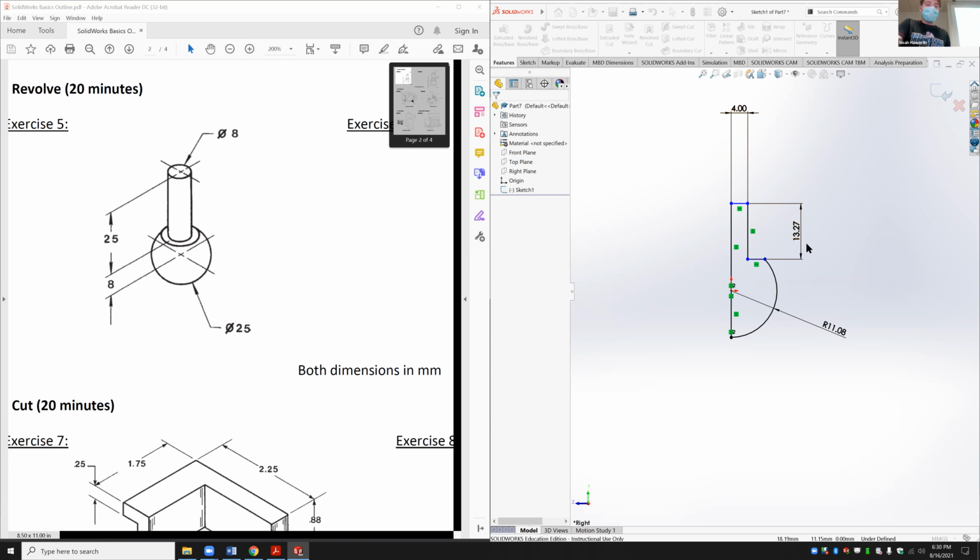Okay, yeah, you don't need the relation strictly for the trim command to work. All you need is lines to intersect with each other. I mean, if there is a relation, then there should be intersection, right? It depends on which relation you're using. If you're using a corner, it's like an intersection relation. There's also a coincident relation. Yeah, it's a coincident. Okay, I see. Let me know if that does not fix your issue.